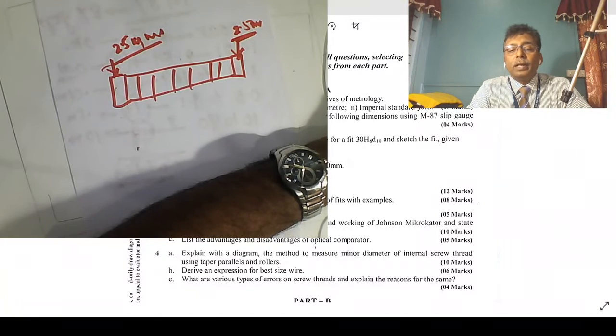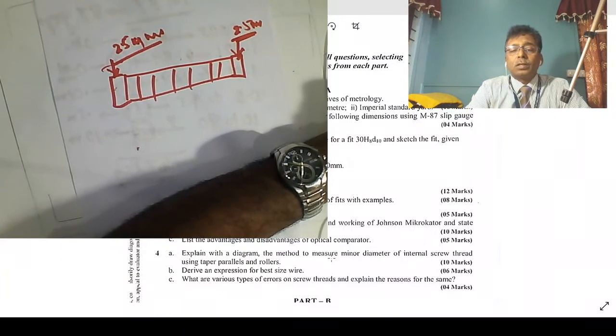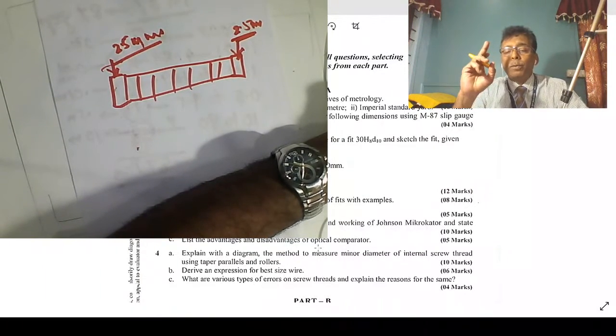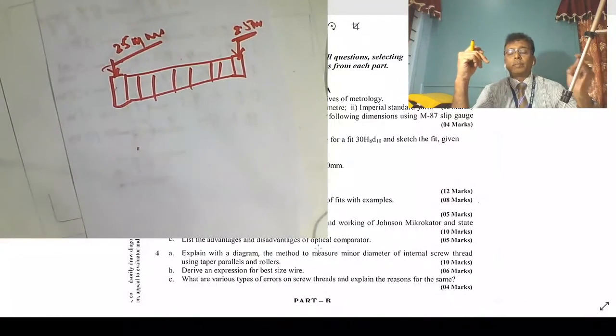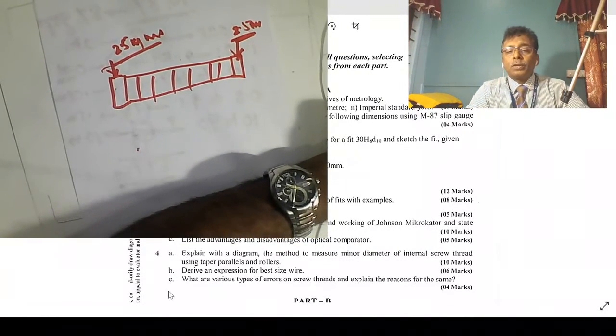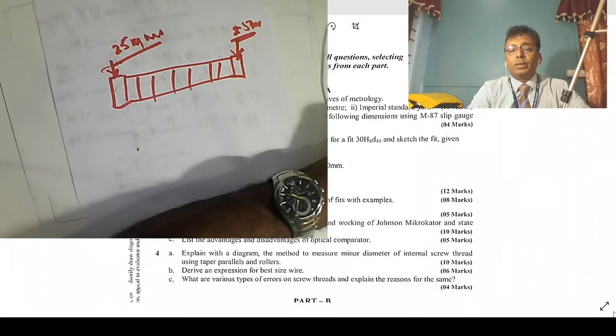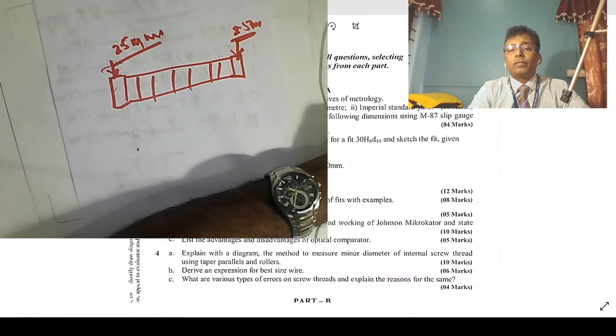92.357 minus 5. Next, what remains is 87.357. Then go to the last decimal. Always start from the last. One more important aspect in building the slip gauges is to try to use the minimum number of slip gauges. Okay. So this becomes 86.350. I have used 1.007, one slip gauge. What remains is 86.350. Can you see this? 86.350 because 1.007 is reduced.